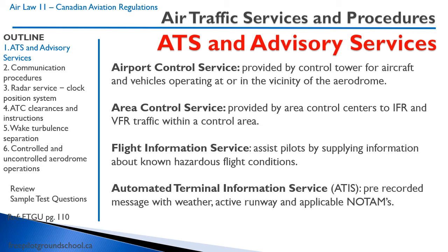Flight information service assists pilots by supplying information about known hazardous flight conditions, and an automated terminal information service is a pre-recorded message with weather, active runway, and applicable NOTAMs. The primary goal is to reduce frequency congestion. You just tune up that frequency, listen to it, write it down, and then when you actually call tower, they do not need to repeat it for you.